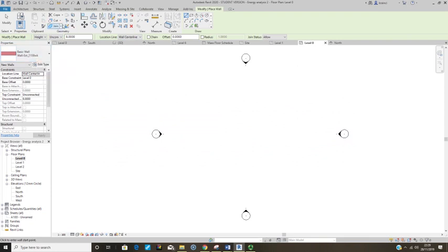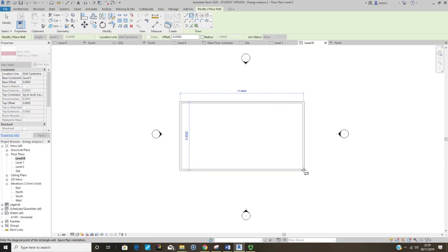And now we can place the wall, easiest would be just with a rectangle. Before I select it, the height of the wall is to level 2, and the location, we can accept wall center line. In the horizontal direction we have 30, and in vertical 20 meters.